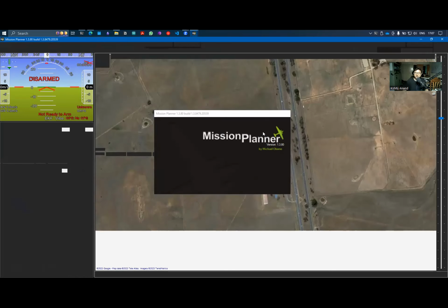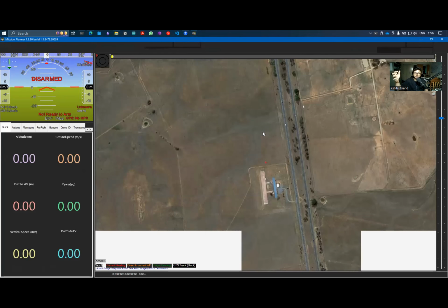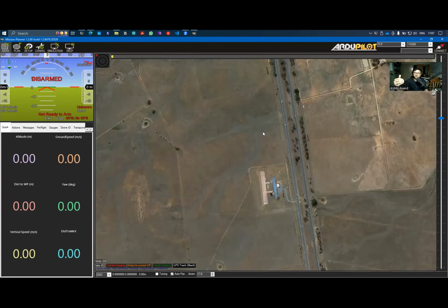I hope you can see, this is ground control station software. You install this on your PC, and when you connect the autopilot to it, you'll be able to program it and retrieve a lot of data from it. So now I am inserting this micro USB B connector into the autopilot, and you see it starts to blink. Okay, it's switched on.